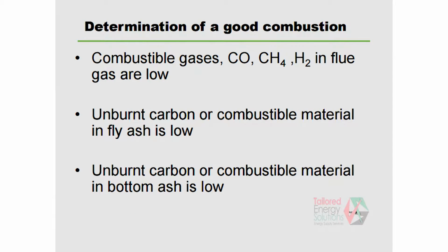How are we going to determine a good combustion? We always say, if the combustible gases in the flue gas are low, and the unburned carbon in the bottom ash or in the fly ash is very low, that's how we can evaluate good or bad combustion.